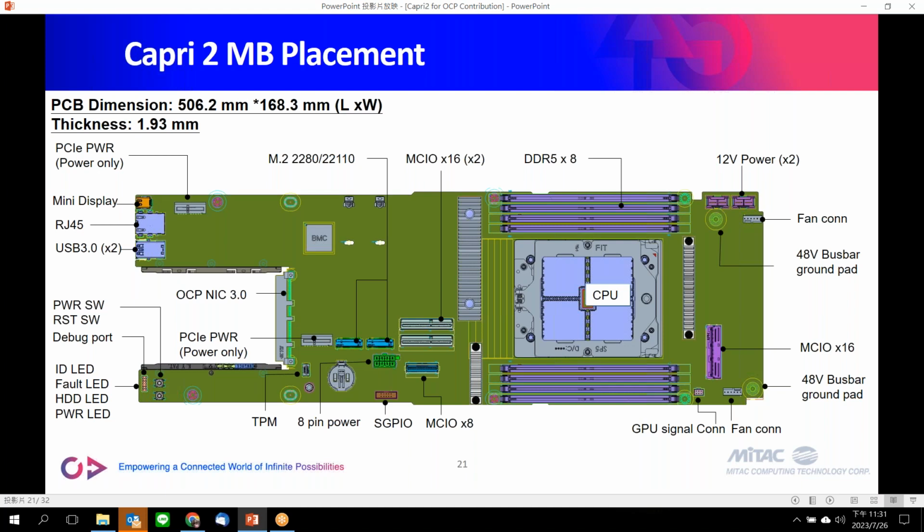If you were to cut that board off right at where the OCP NIC connector is, you could really reduce the cost of this baseboard and go with a more modular approach. Instead of your ID and fault LED stuff, that could be a small, very cheap board, maybe 4 layers, and you could change layers and things for your DCSCM to be different than your motherboard.